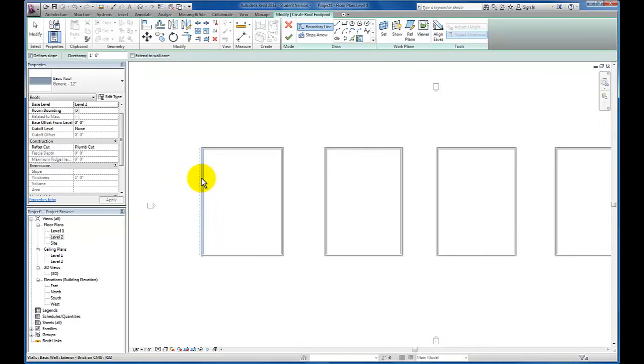We're going to keep that on the outside, and I'm just going to click on each one of my exterior walls, and you'll see Revit actually cleans up this sketch for me as I select my exterior walls. If I need to switch the orientation of my wall, I still have this symbol, and you'll see it actually brought the sketch to the outside face of both of my walls, 1'6". I'm going to keep that on the exterior, and this right here allows me to change the slope.